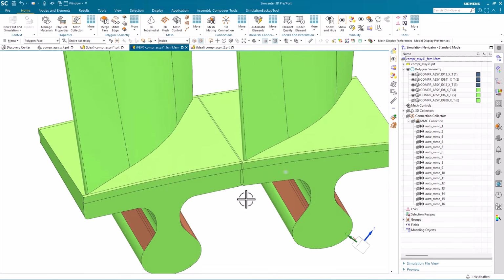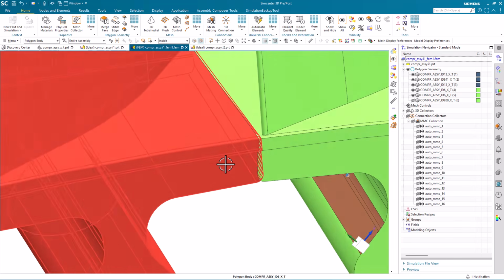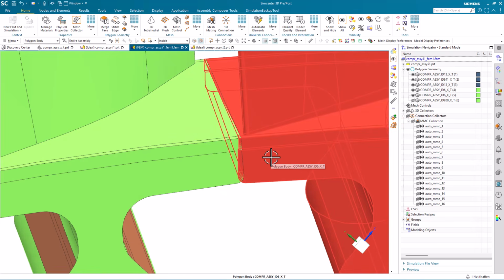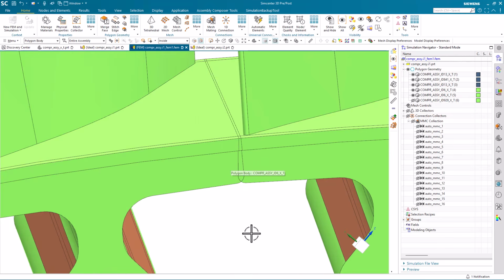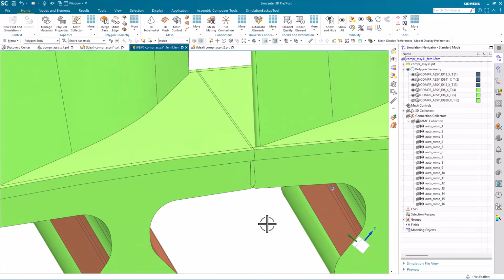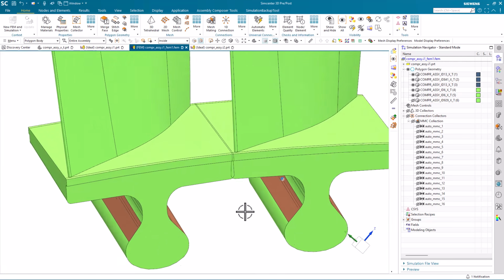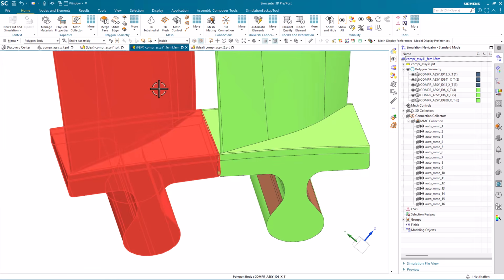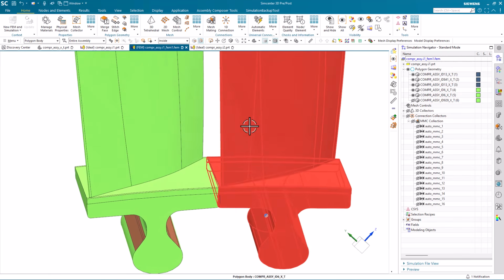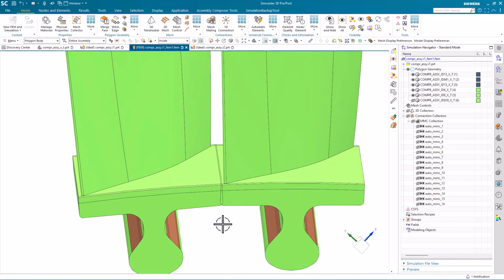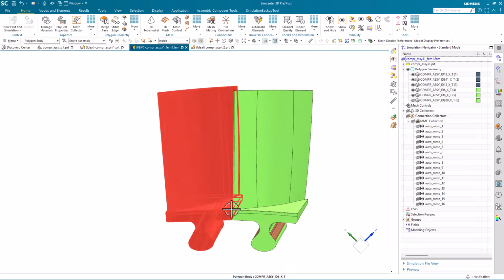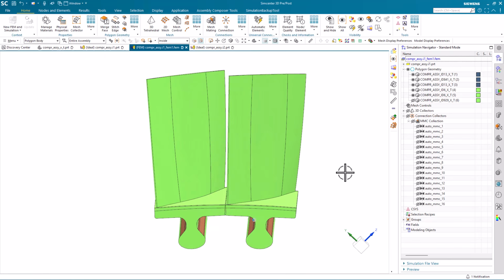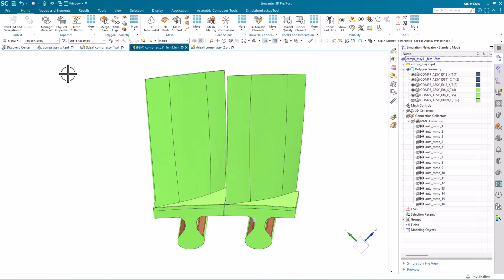And then what do we have with respect to our interference condition? So we have nothing really. Nothing happened in terms of mesh mating because these surfaces aren't touching within one another. The interference was greater than that search distance. So nothing actually happened in this case for mesh mating conditions. So we don't have a connection between adjacent compressor blades at that location. So that's kind of a problem. That's really the connection that you want to have, the most important connection of the connections shown here.